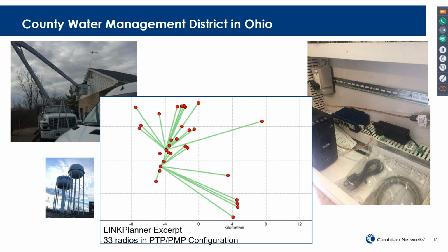After studying the situation, we advised them to run an overlay of 900 megahertz unlicensed and 700 licensed, so that you can get the critical data over the 700 network. The thing is that this customer cannot afford to lose any bits. If the SCADA message does not pass through, the water quality would suffer.